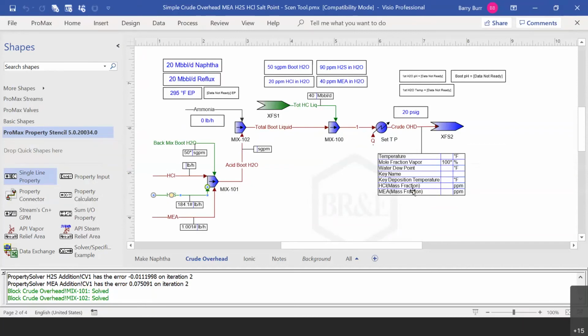With the subcooled reflux, there is a chance for non-equilibrium third phase formation. With a subcooled reflux, and if you don't have the water boot, in our simulation, if you don't add some entrainment specification, you just leave it as an ideal stage flash, the water from the aqueous phase will be removed as a third phase.